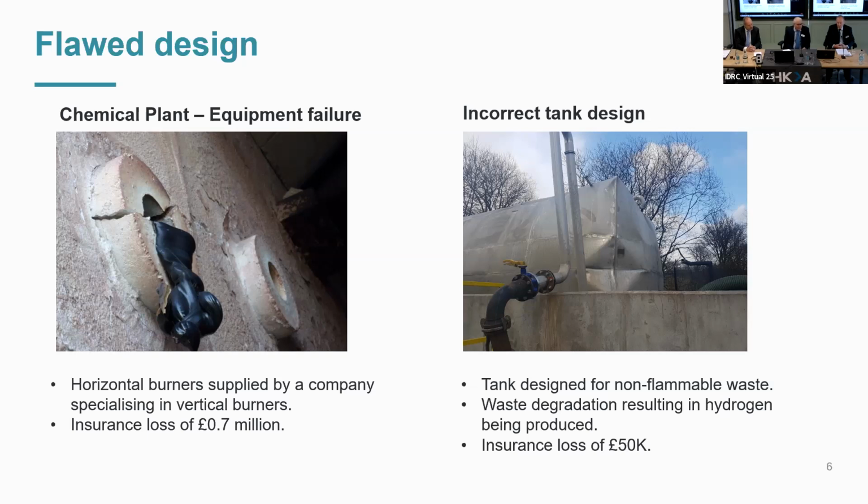The second was a tank design for non-flammable liquids and waste, but what wasn't taken into account was the waste degraded and generated hydrogen. The hydrogen then ignited and there was a mini explosion. Again, fortunately, nobody was injured.